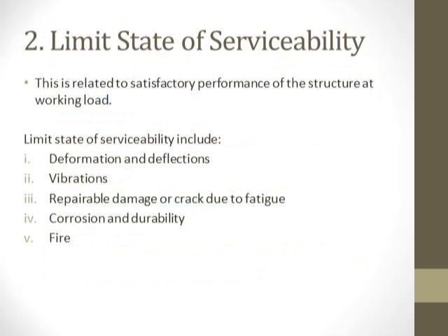Now next is the limit state of serviceability. This is related to the satisfactory performance of the structure at the working load. These limit states deal with the discomfort to the occupancy or malfunction caused by excessive vibration, deflection, corrosion, etc. Here I have listed the same.